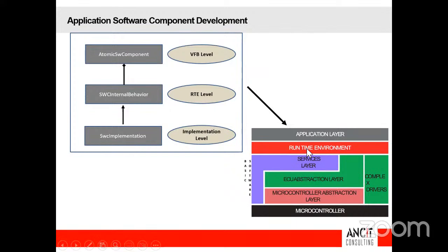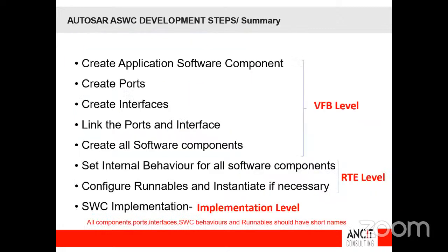The runtime environment is the heart of the AUTOSAR architecture, serving as an interface between the application software component, where your entire logic is sitting, and your BSW stack, which is responsible for talking to the microcontroller or the underlying board. So the runtime environment is responsible for bridging the gap between these two. That's the basic idea.